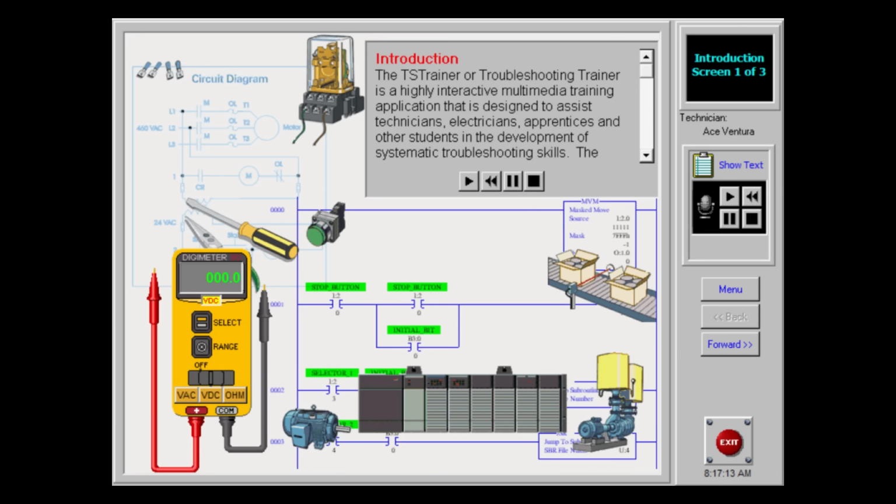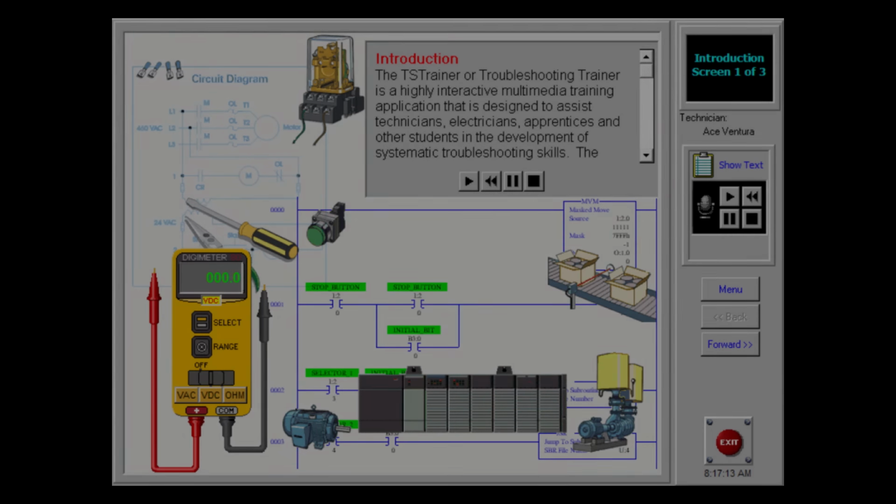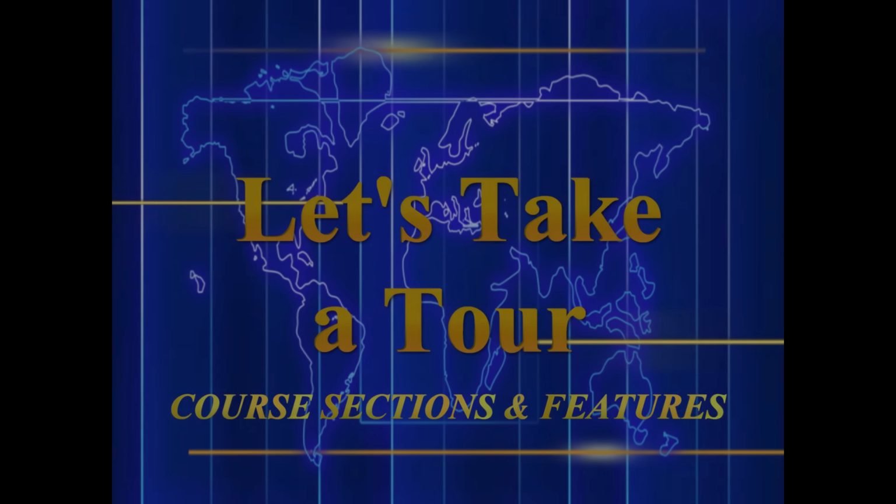Since the wiring and the inputs and outputs, I/Os, are the most vulnerable elements in a system, examine them first. While talking to people and reviewing information, look for a reoccurrence or pattern. If a pattern exists, is it related to shift changes, process changes, or any other reoccurring event? Use your own judgment on when to quit gathering information.